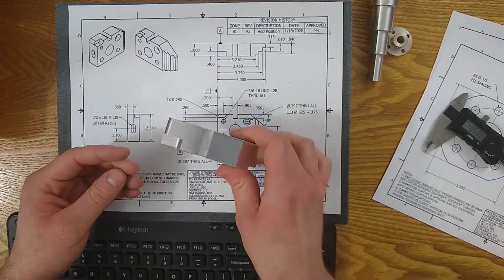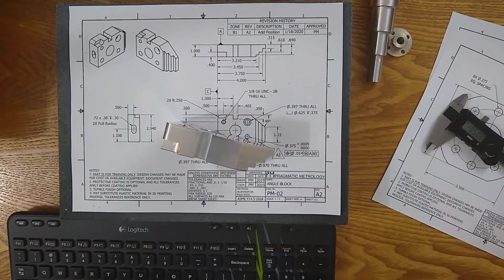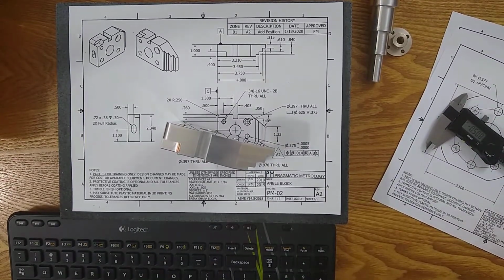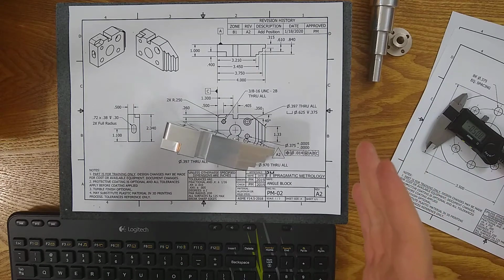The other method that I recommend, if you're not going to go view by view, go feature by feature. And what you want to do is verify the size, verify the location, verify the orientation, and verify the form. So those are the critical parts of every feature. How big is it? Where is it located? Is it pointed, kind of angled, oriented the right direction? Because you can locate something, but it'll be pointing the wrong direction. And then the form error, right? I already talked about circularity or flatness. That may not be stated on the prints, but have a big effect on whether a part passes or not.